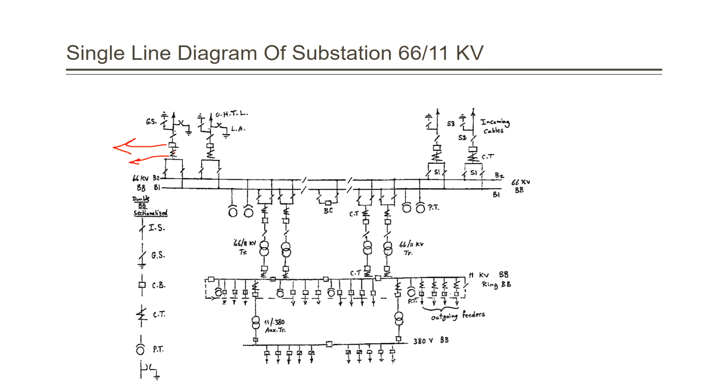The current transformer is connected to the relay, which is the brain which controls the circuit breaker. So when the relay senses that the current exceeds the pickup current, the circuit breaker starts to switch off our circuit.